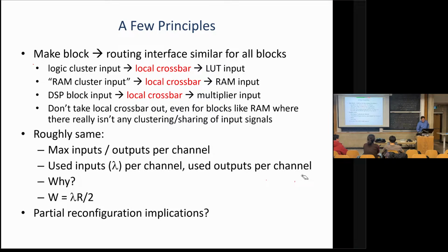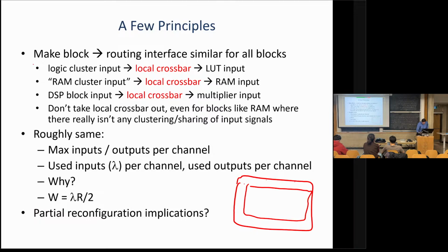Yeah, that could be a good use case. And in fact, data centers do, as I showed you in Catapult, take essentially the periphery of the design where all the high-speed I/O is and so on. They build what they call a shell, and it's got some management layers, and it simplifies talking to everything. It's all pre-done, placed and routed, locked down. And then they actually do partially reconfigure what's inside. What that allows them to do is put in different accelerators without taking down the IOs, which might actually have bad consequences for the system.